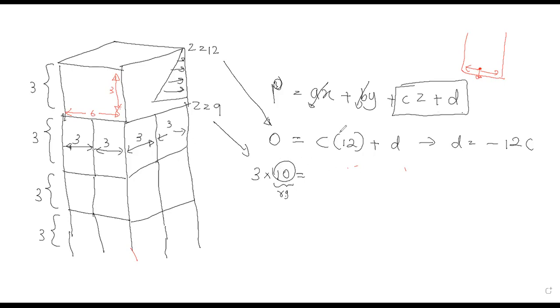So we usually take rho G as 1 unit and multiply the H value. I think better to check it. I think this is in kilonewtons per meter cube. So once you multiply it by a meter unit, always make sure the units are consistent with your system that you are modeling. So you know what you're modeling, and this is 3 meters, so that's okay.